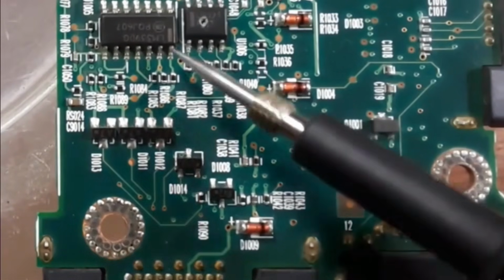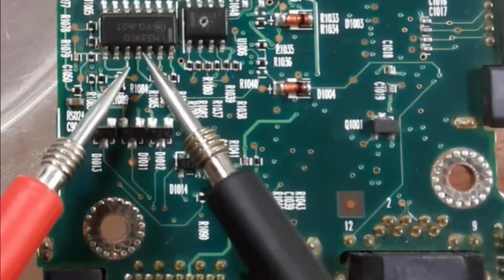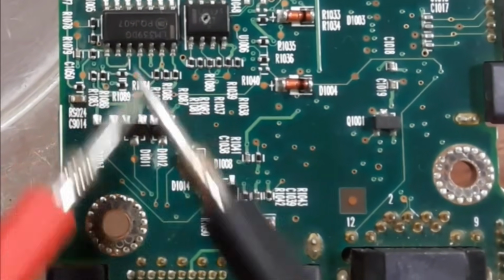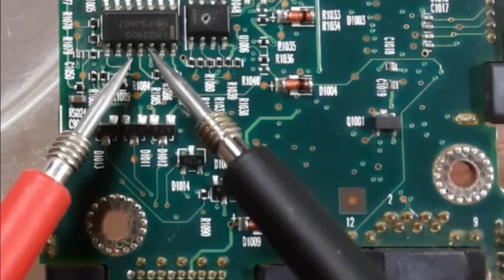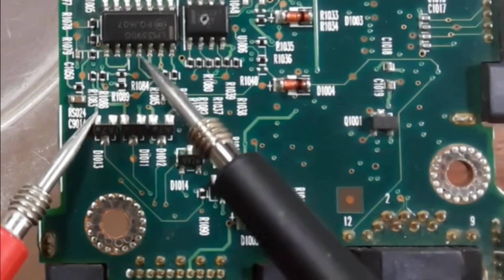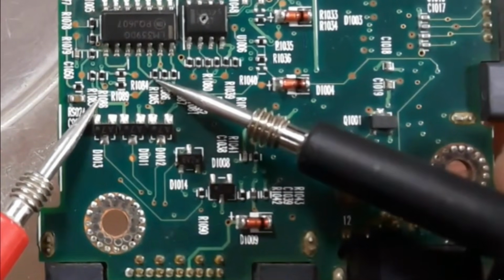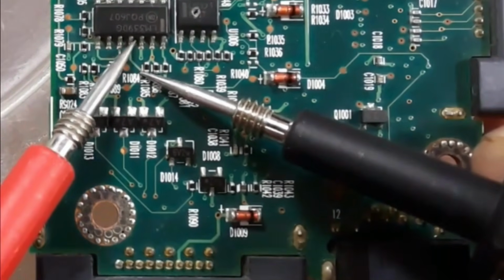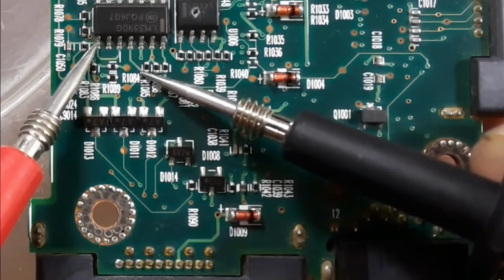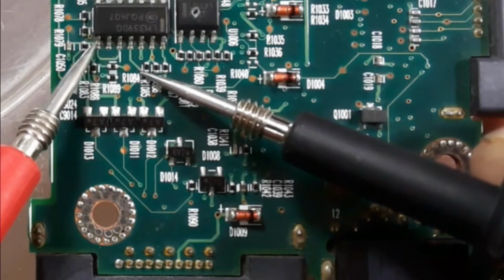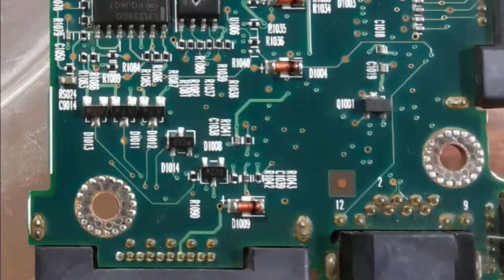We have here this IC, as you see. Do you see the extension here? So avoid taking measurements here because you can cause a short circuit. But if I want to take a measurement, for example, between these 2, I can look for the extension of this pin. This is its extension in this resistor. We can check, as you can see. And for this, its extension is here, because these 2 pins are connected together, as you can see.